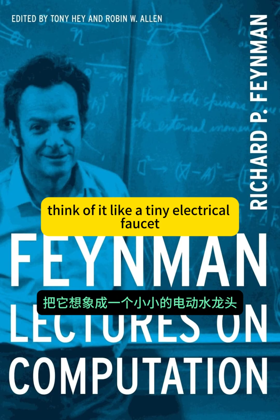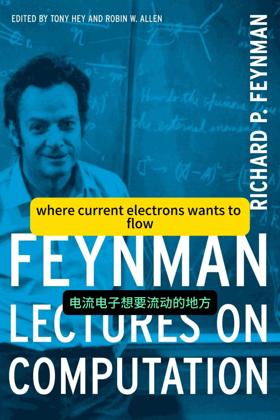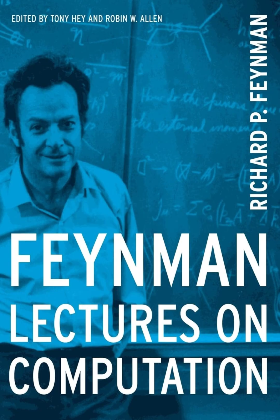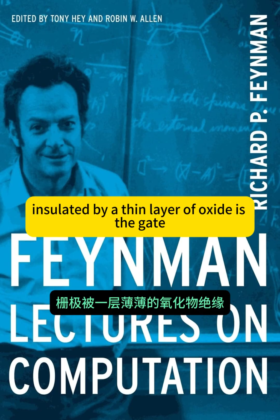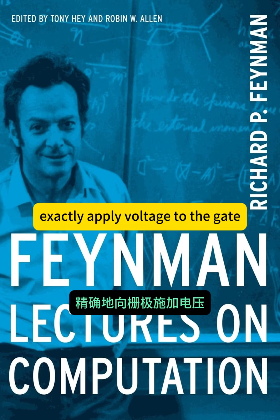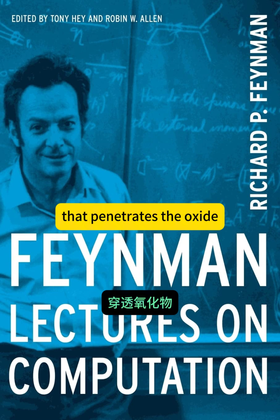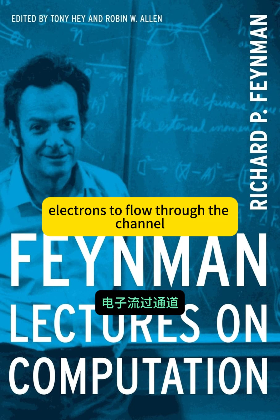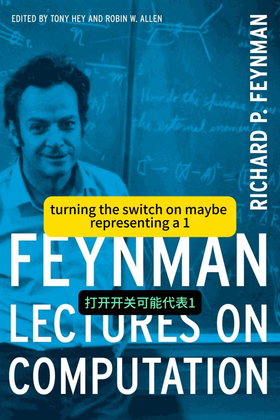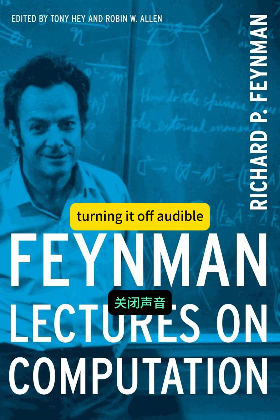Think of it like a tiny electrical faucet. You have a source and a drain where current, electrons, want to flow. Between them is a channel. Over the channel, insulated by a thin layer of oxide, is the gate. And the gate controls the flow. Exactly. Apply voltage to the gate. This creates an electric field that penetrates the oxide and either allows electrons to flow through the channel, turning the switch on, maybe representing a 1, or blocks the flow, turning it off.